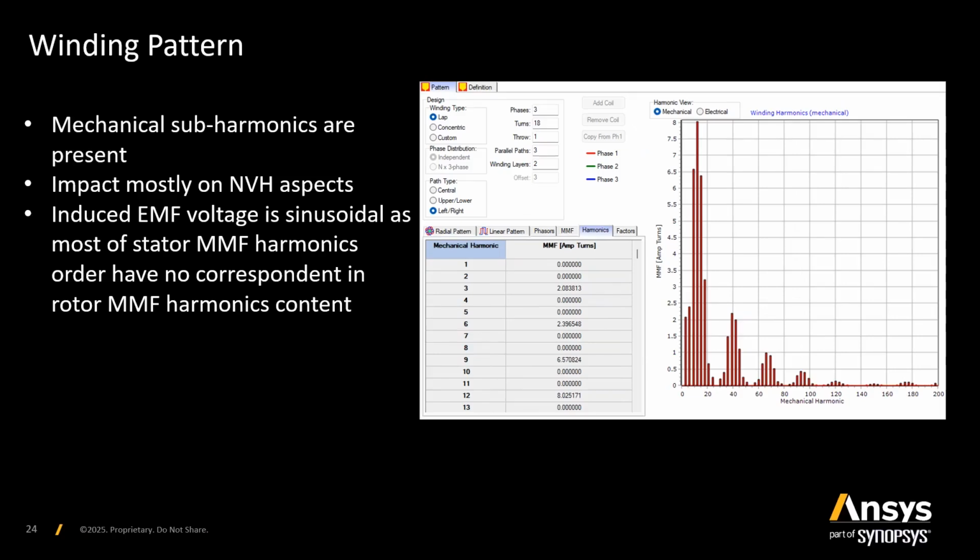So even though the spectrum of harmonics may be quite significant, because the rotor field doesn't contain the same order of harmonics, the interaction between harmonics of the same order is limited, and in the end the performance of this machine is quite good.